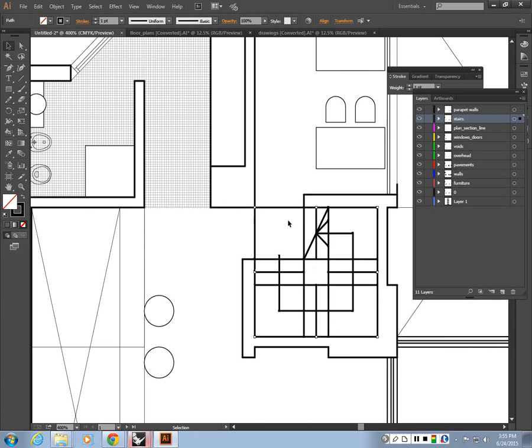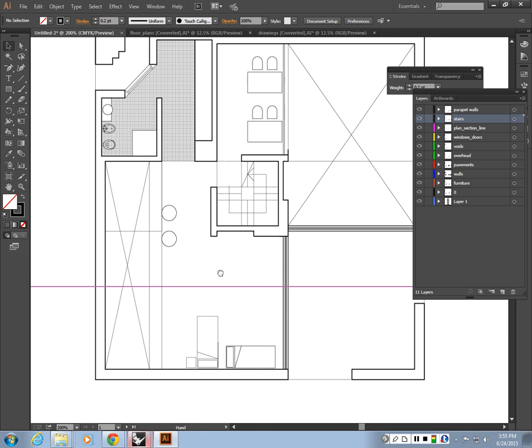So I can select these elements, or just directly select them here, and I can make these type of decisions. So maybe these, if you want to assign them a specific line weight, you could also go up here. It's right now 1 point. I want to make them 0.2. I can make them lighter, right? So I can assign line weights like this, customize my drawing. And the main point of assigning line weights is the hierarchy, right? Separating structural elements, cut elements from elements in elevation, elements that are further away from our view.